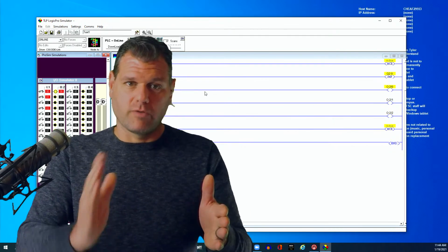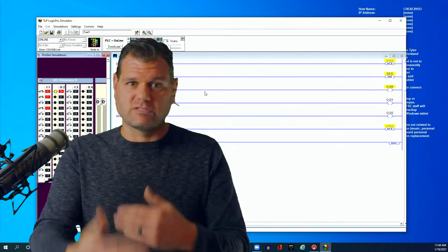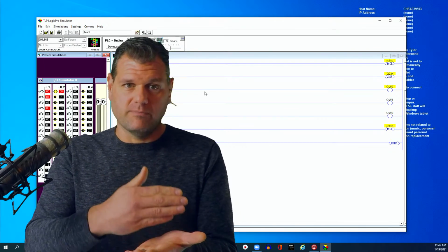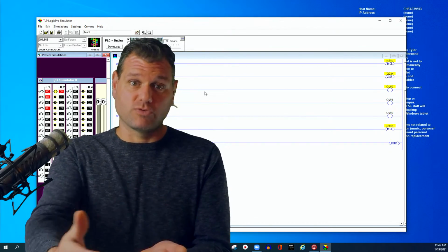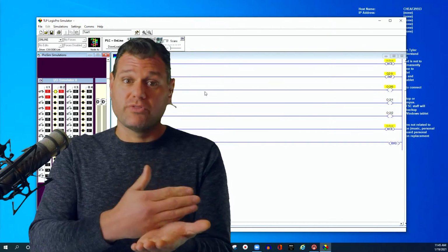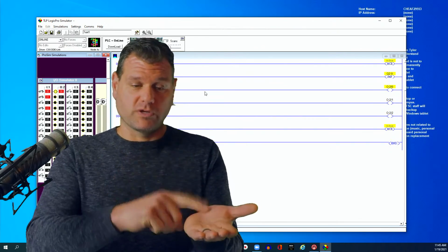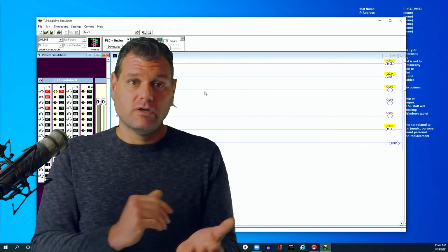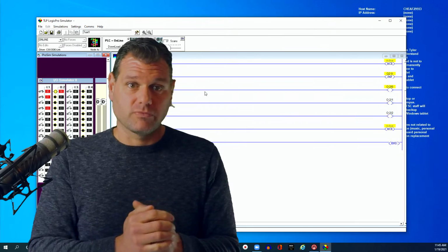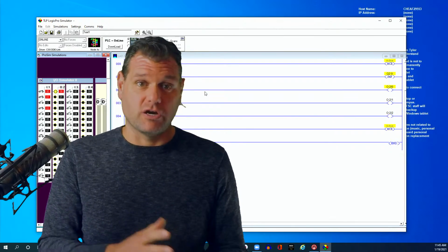If it reaches over temperature, it shuts off, or when it reaches the end of its stroke, it says stop motor, because I don't want to keep driving into something. If that's one of the conditions and you jump over that section, the motor is going to stay on regardless. If you hit that limit switch saying it's reached its end of travel, that motor is going to keep on trucking, because you completely skipped over it and it never scanned whether the switch is on or off.